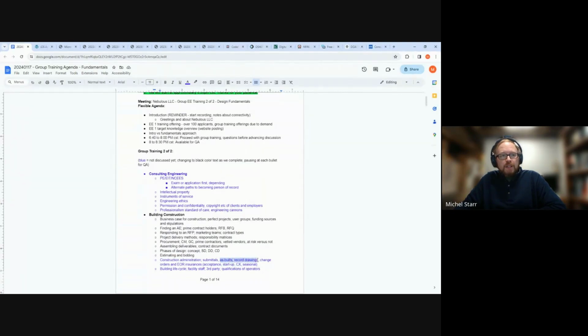As-built and record drawings: the contractors likely have requirements through standard specifications. The most common specifications issued would have them do this as a standard of care as well, marking plans along the way as they're installing, and then at the end, if it is in the contract to do so, or otherwise it usually is a standard of care, especially in that lump sum situation, to provide record drawings, which means the engineer receives those paper markings from the contractor and updates them in electronic software.